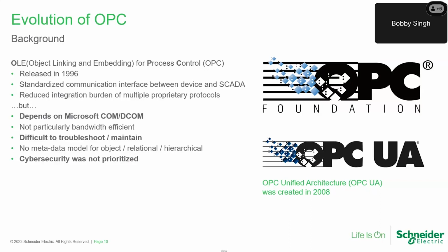Okay, so the OPC protocol was created in 1996 with the purpose to abstract PLC-specific protocols such as Modbus or Profibus into a standard protocol for HMI and SCADA systems to interface with. What this did was it allowed software vendors to develop products based on a single standardized protocol rather than needing to support multiple vendor-specific drivers. OPC was founded by and is managed by the OPC Foundation.